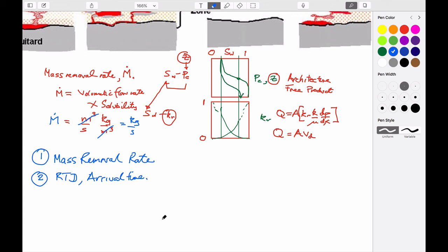What was I thinking? So, you've already been exposed to residence time distributions. You know, for instance, that if this is at Darcy velocity, the advective velocity is equal to the Darcy velocity divided by porosity. Or this would be the Darcy velocity divided by the volumetric moisture content, which we talked about last time for Brooks-Corey. And so we can always calculate exactly what that would be.